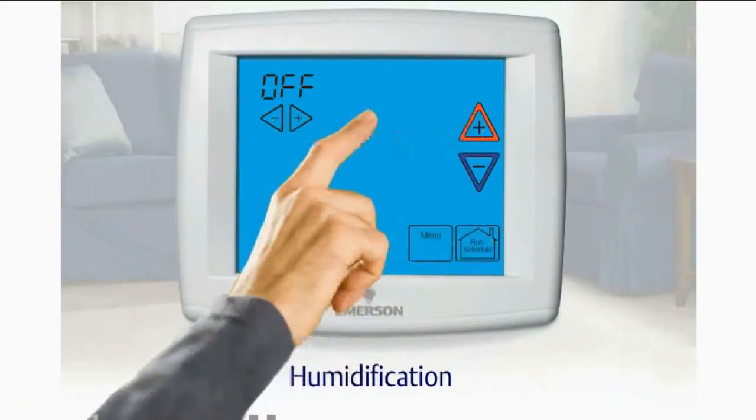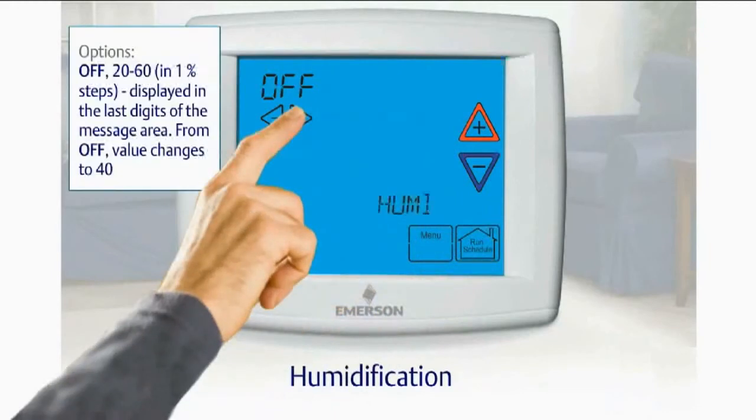Menu item 13 is humidification. You have a choice between 20 and 60% relative humidity. If relative humidity is below the setting, the HM2 output is then activated with a call for heat. To turn this feature off, lower the setting to its lowest level of 20%.